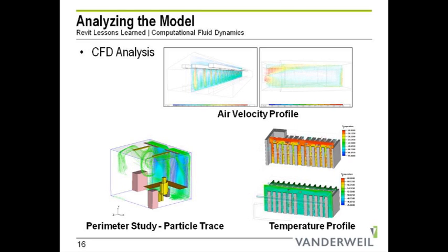We're talking about airflow, how airflow mixes in a space, how the temperature is controlled not only in the room but throughout the entire space. You're figuring out where things are going and how fast things are moving. And there's so many calculations that have to go on that it's very rarely or never that you will use a Revit model in a CFD program.